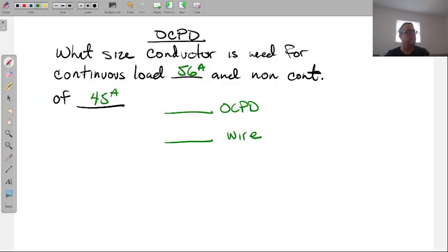All right, take your time. Use your notes. There's one giant note we need, which addresses the percentage that we're applying to one of these specifically. It's the one giant note you need for wire selecting and breaker selection. Don't forget the 125 for continuous. From there, the 2 tables, which I'll also add here.